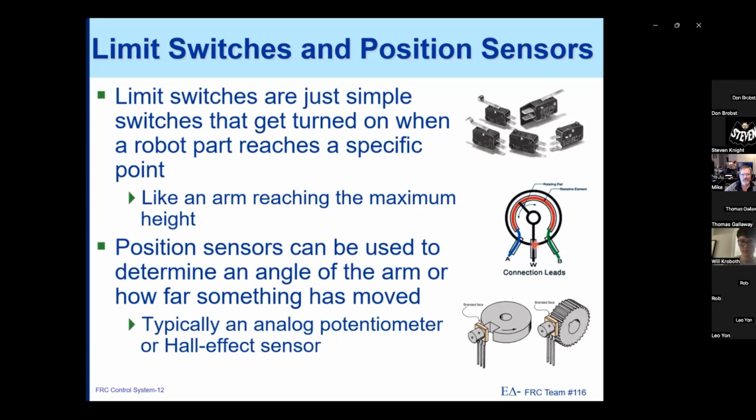We also have another type of sensor called an analog sensor. This is a potentiometer. In the potentiometer, we have voltage coming in, voltage going out, and then we have this thing called the wiper, the center rotator. As this individual arm moves around on this track, we then get varying voltages out of this. Because there are any number of voltages that could potentially be represented by this particular signal, this is referred to as an analog sensor. And an analog sensor would then be wired into the analog in ports on the RoboRio.